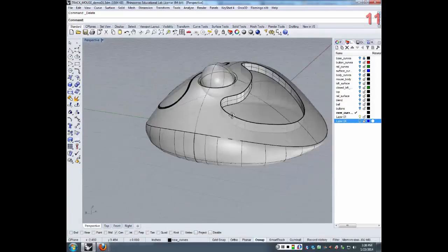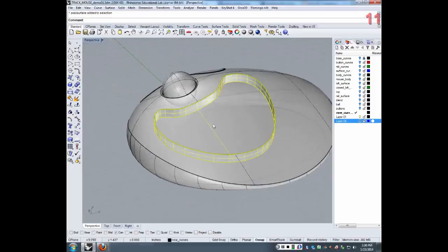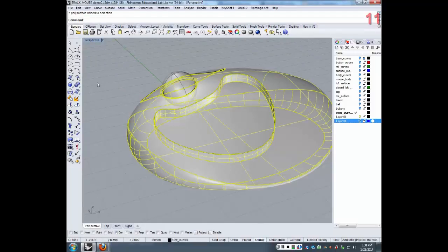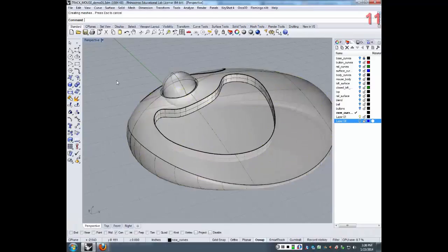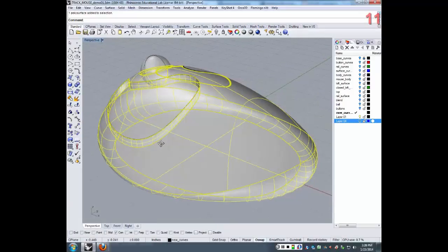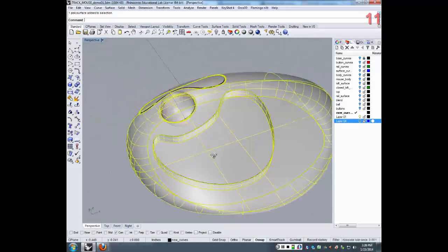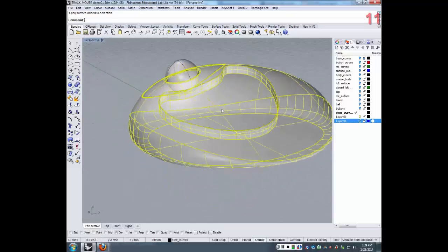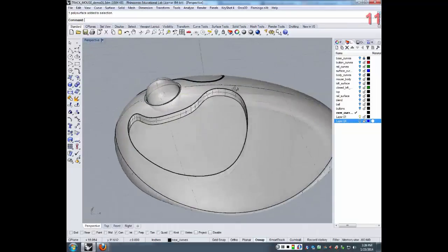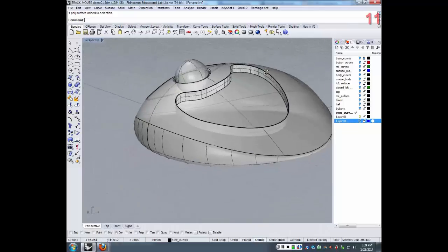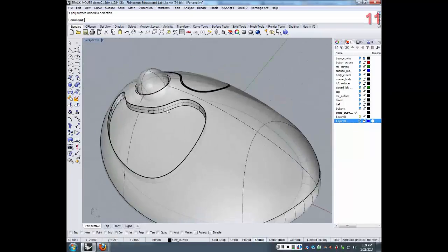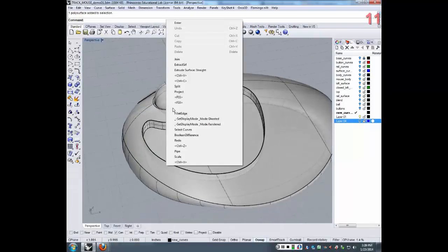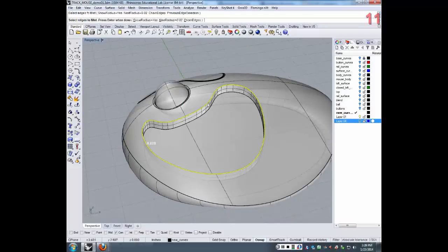And so now I got this cavity, right? And I want to take that and join that to that. So that's all one big happy family, right? And I'm basically going to use this to create a cavity for my button. Okay? For my little clicker here. That's a little thick, okay? So let me go here. I'm going to fillet this edge. Okay? And I'm going to make the next radius 0.1.